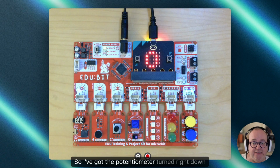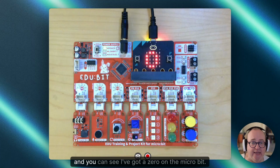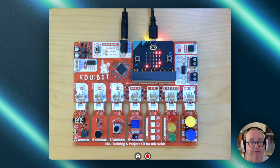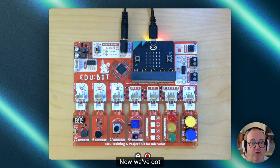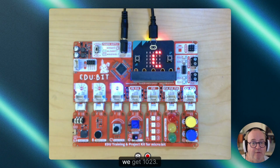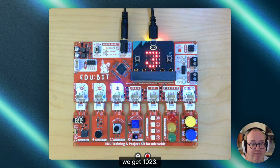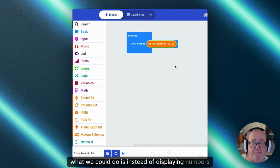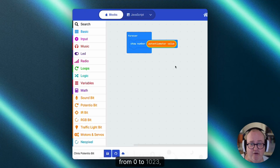So I've got the potentiometer turned right down, and you can see I've got a 0 on the microbit. If I turn it up just a little bit, now we've got 273, and if I turn it up all the way, we get 1023. That works. What we could do is, instead of displaying numbers from 0 to 1023, we could restrict it